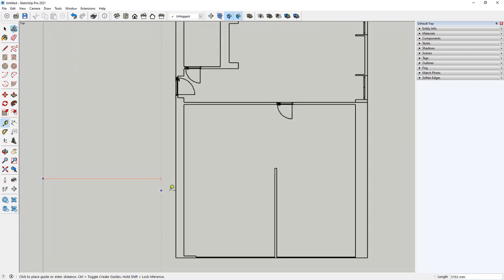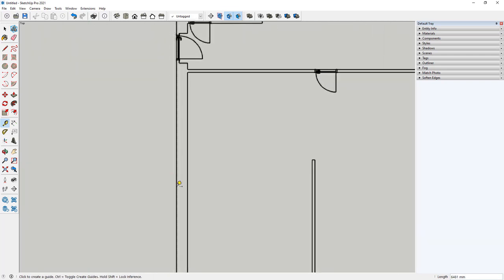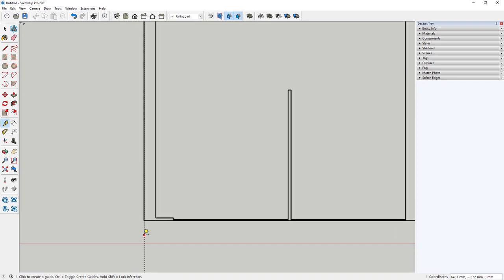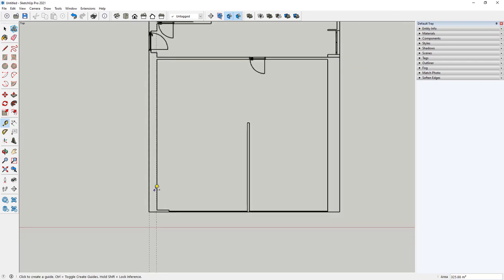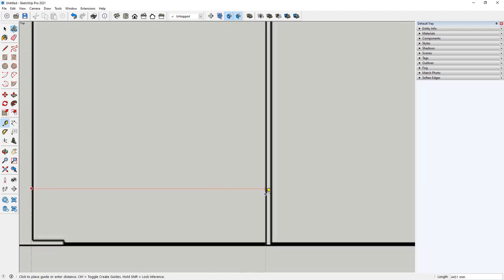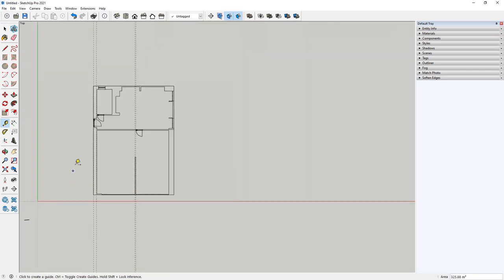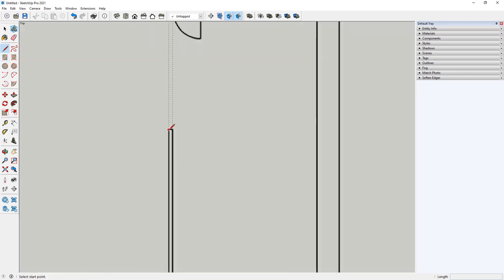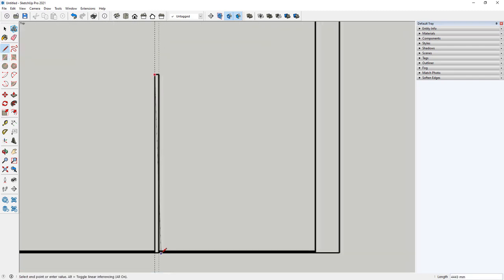The reference lines come from the horizontal and vertical axis, and we just offset each reference line by some dimension to cover all the walls, as you can see how I made it right now.